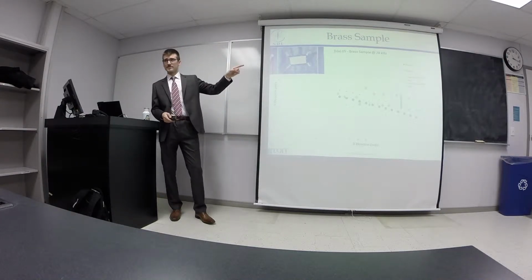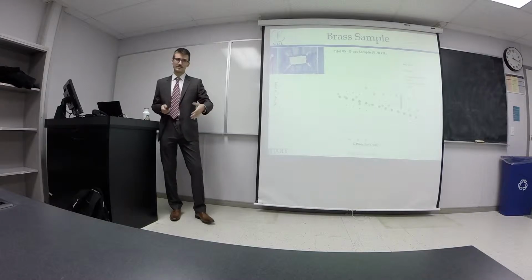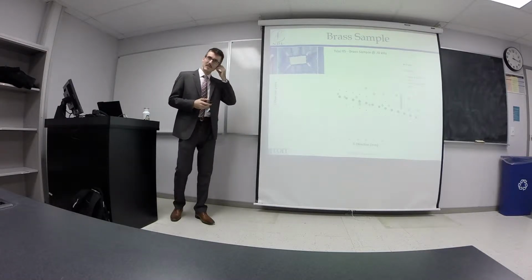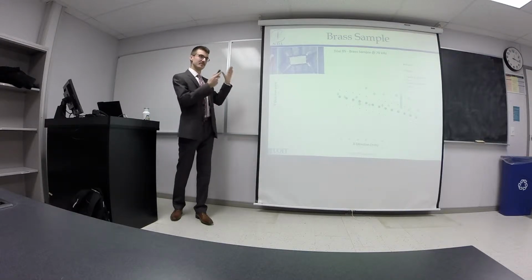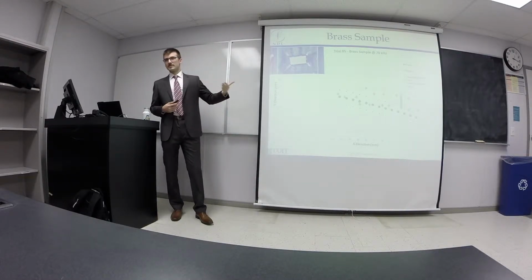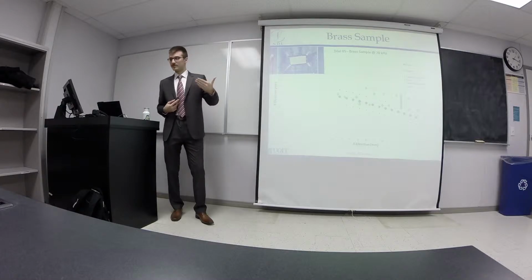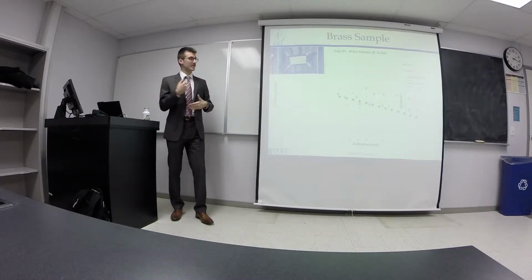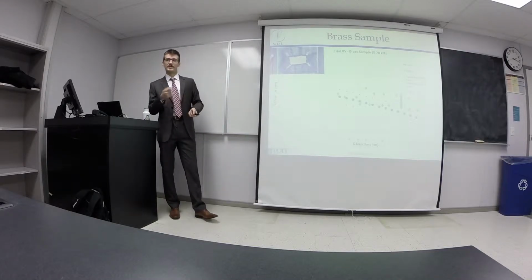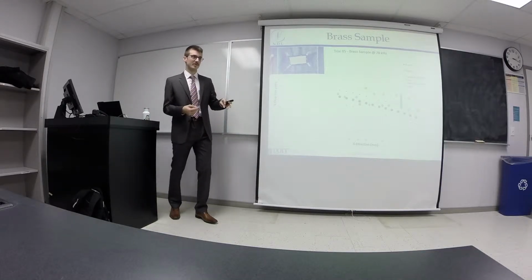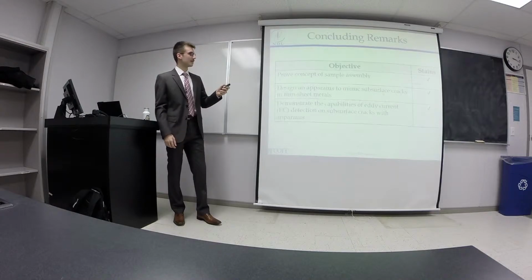You'll notice that it's actually 70 kilohertz and not 40 kilohertz. This is because we're not sure what kind of composition this brass is made out of, and because of that, the material properties might vary from what I expected when I calculated them. So this essentially shows the skill of the operator that's required in the field when you're trying to detect something of unknown material composition and stuff like that.